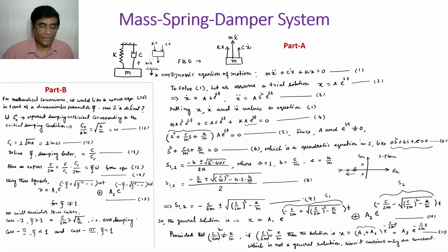This observation is from here. So whatever values m, c, k may have, the e to the power something will always be negative. And if we plot them in the S plane or Argand diagram, then the roots will always be in the negative half of the diagram, either here or here, right? It can never, ever be here, or here. And that is why a second order system will be asymptotically stable. All kinds of things we will discuss when we discuss control, but the understanding is here.